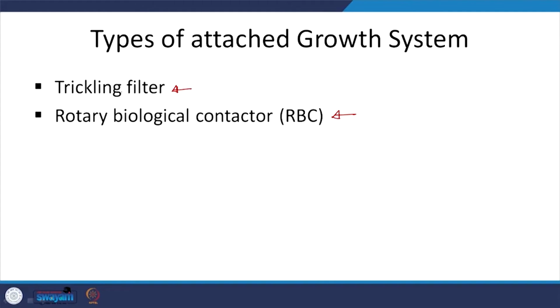Another one is the trickling filter, but when we think of a filter, we think of, let us say, activated carbon or a sand filter, but then the head loss will be too high, right, and you will have clogging way too often. It is not a filter per se, but only a different kind of media that gives a surface for the microbes to thrive upon. But again, let us look at these aspects and move on.